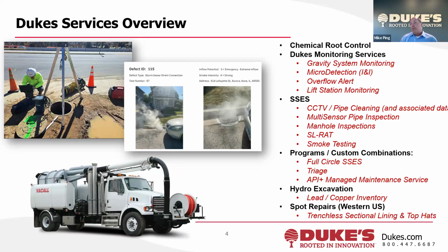We do lots of monitoring. A lot of that is centered around what's called I&I, inflow and infiltration. And we certainly do lots of SSES, as it's called, and it's pipe. This topic includes pipe cleaning, pipe TV, and things like manhole inspections. Then we have programs. We do hydro excavation that's centered around the lead and copper inventory initiative in the U.S. And then mainly in the western part of the U.S., we do trenchless sectional lining and top hats.